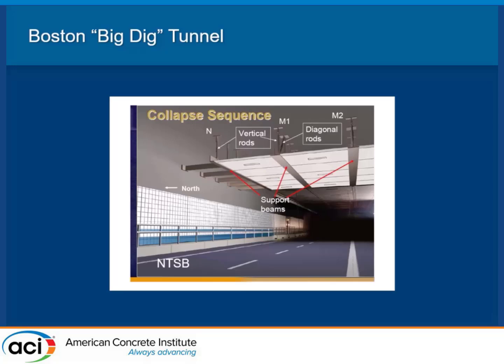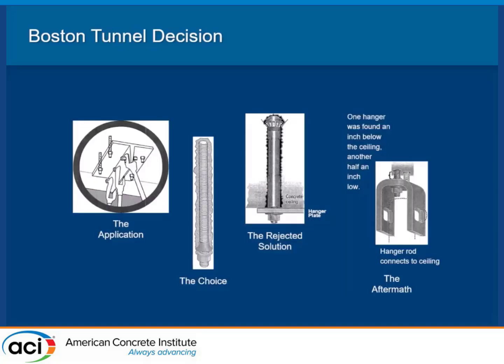The panels were normally 4 inches thick, spanning 12 feet and about 4 feet wide. There were about 20,000 panels in the tunnels. Not all the Boston tunnels used the adhesive anchors; many used channel anchors. In the D Street portal, the ceiling was installed in 1999-2000, well after the cut and cover tunnel was constructed. Ceiling panels had to be designed to accommodate suction load of about 45 psf. The anchor service load was on the order of 2,600 pounds.